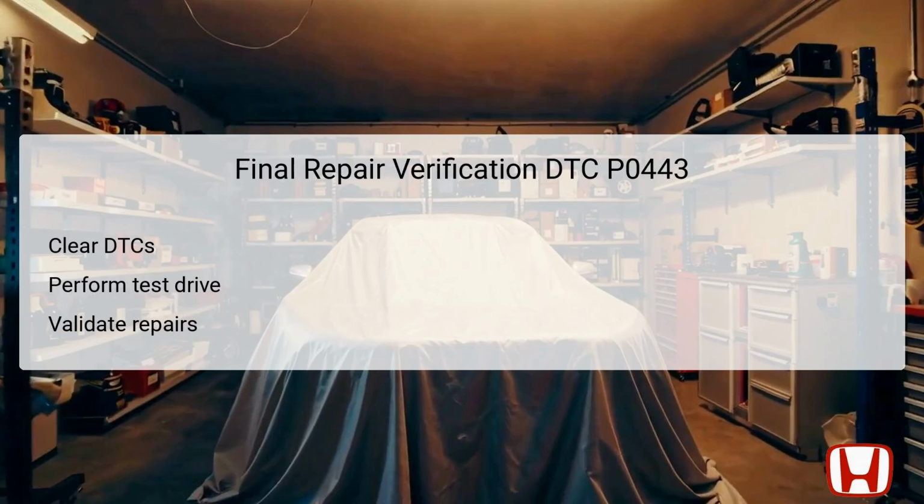Once all necessary repairs have been completed based on troubleshooting findings, it is essential to verify the effectiveness of the repair. The technician should begin by clearing any remaining DTCs from the PCM using the HDS. A follow-up test drive is crucial to ensure all systems are functioning optimally.